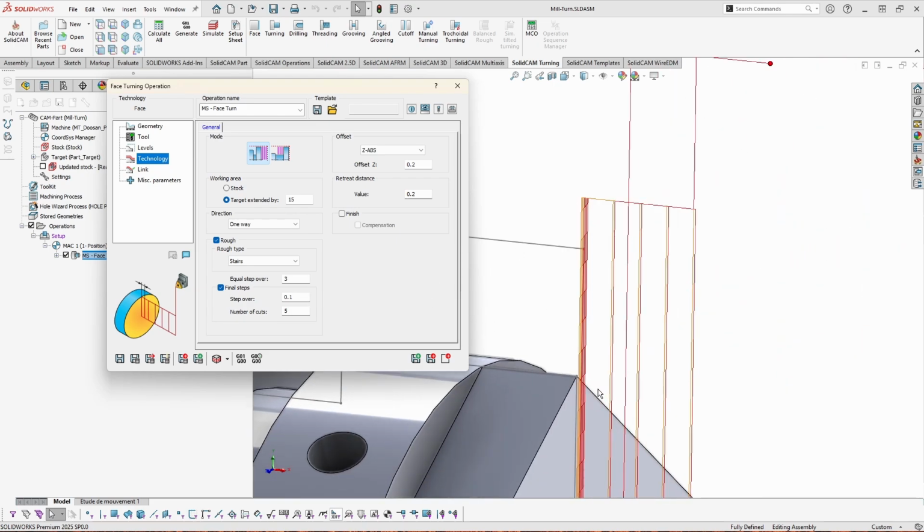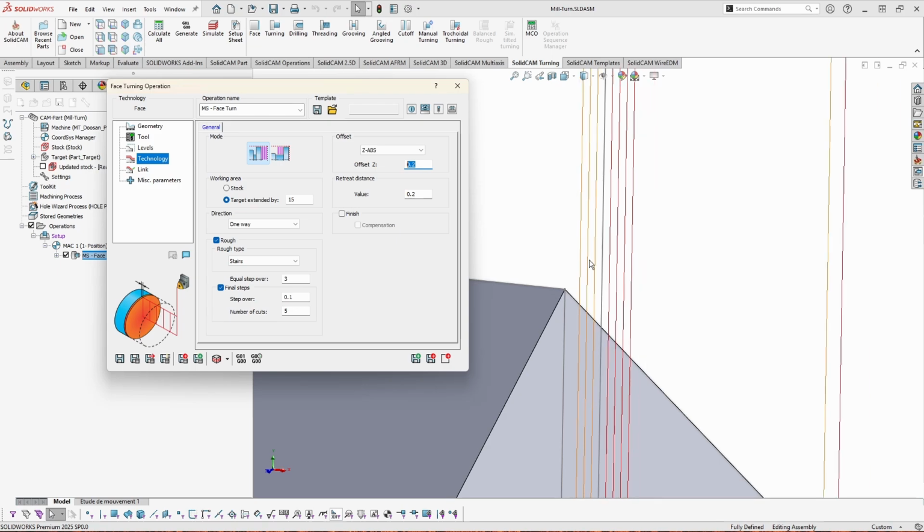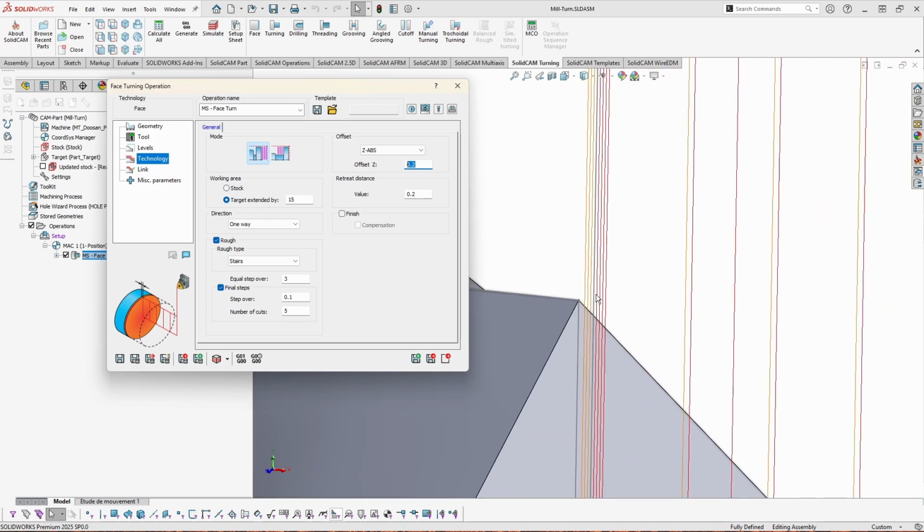millimeter. Now, if you take a look also at the last line of the toolpath, it is in front of the target, and it is exactly by 0.2, which is our offset. The offset here defines the offset from the target model for the stock that we leave for our finishing strategy. For example, we have 2 modes here. Let's try using Z mode and inputting minus 0.2.